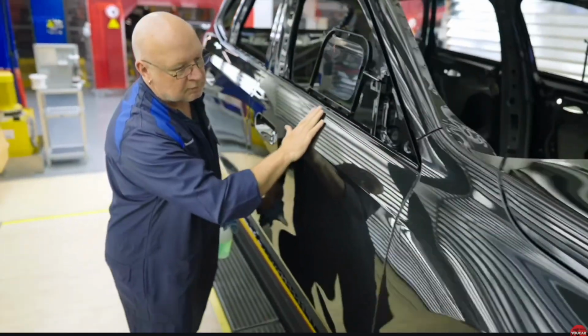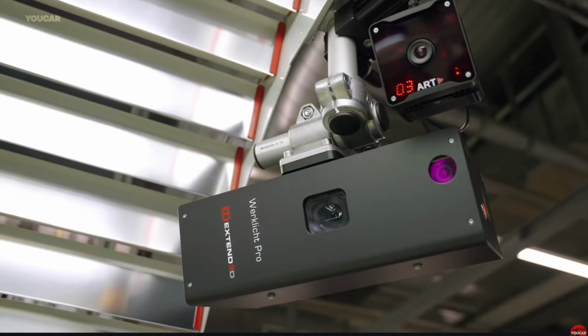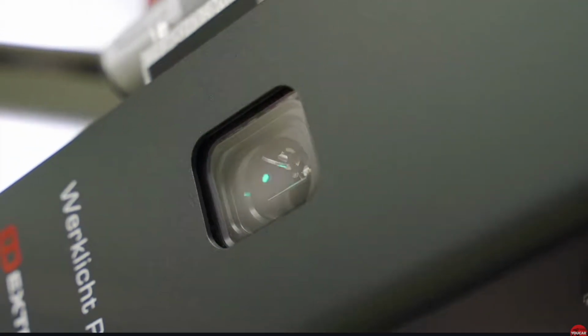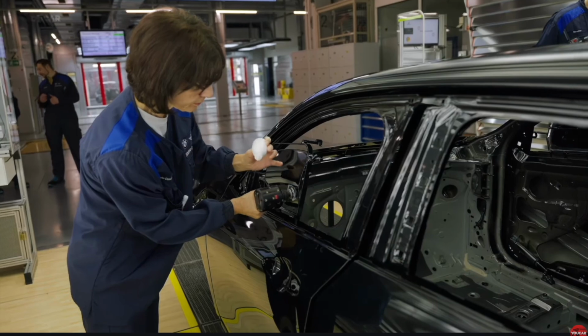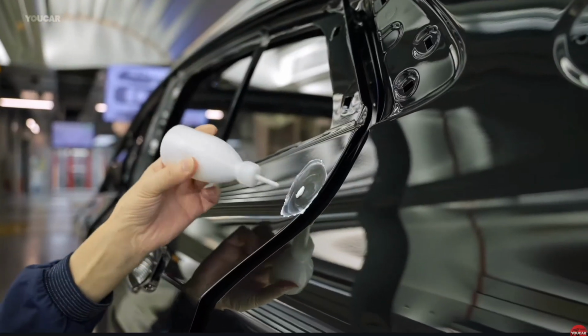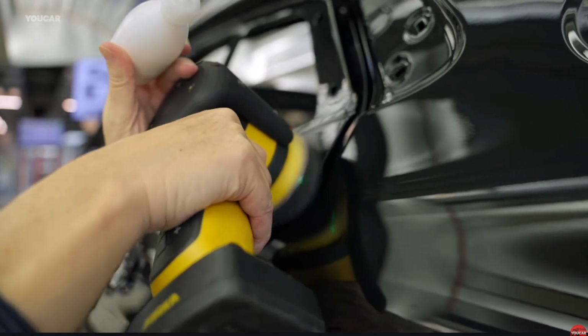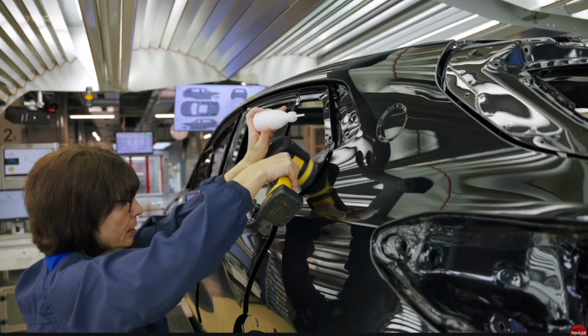There are a few limitations to buffing. One issue is that buffing is not very effective when it comes to fixing large dents or scratches. It's better suited for small defects and small punctures. Another issue is that a surface could be at risk of overbuffing, and the abrasive material could cause more damage if not applied appropriately.